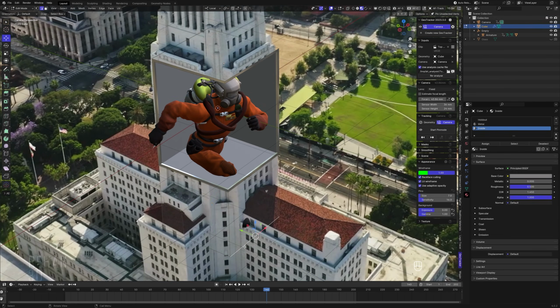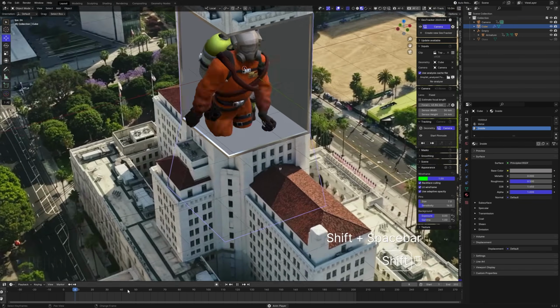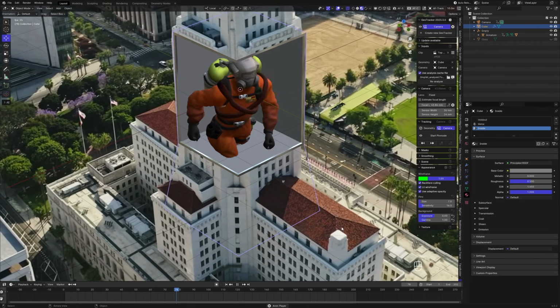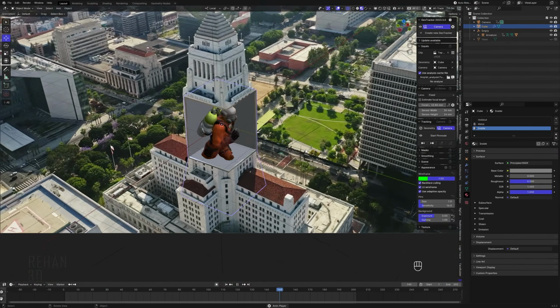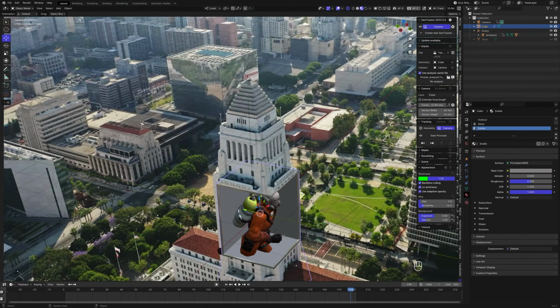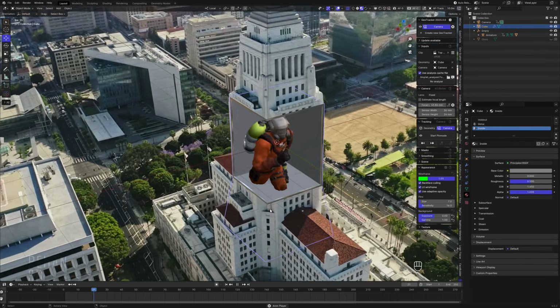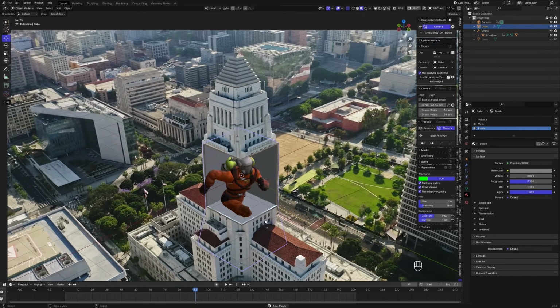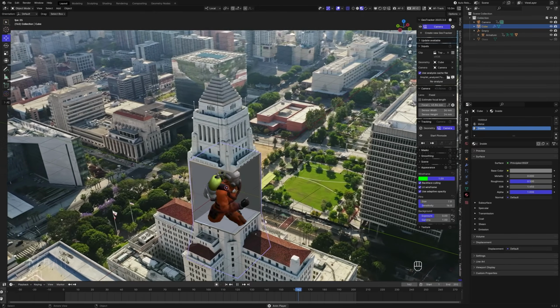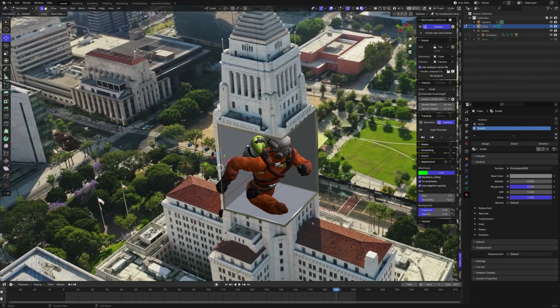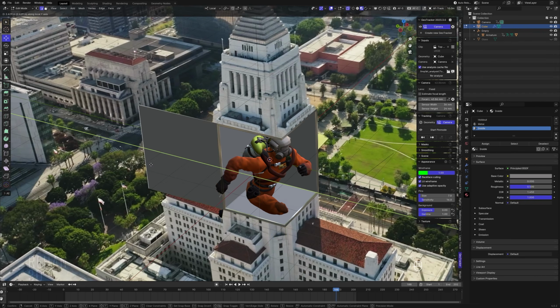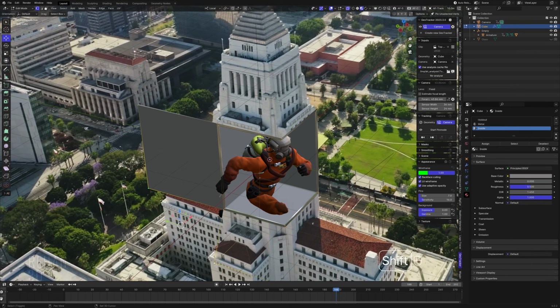Select the cube, click on this shape, this bottom face, and just scale it. And now it starts showing up, and now we are good to go. Okay, so let's select this face and extrude it on the Y, and select this face and press F to create a face, and select this edge and create a new face here.